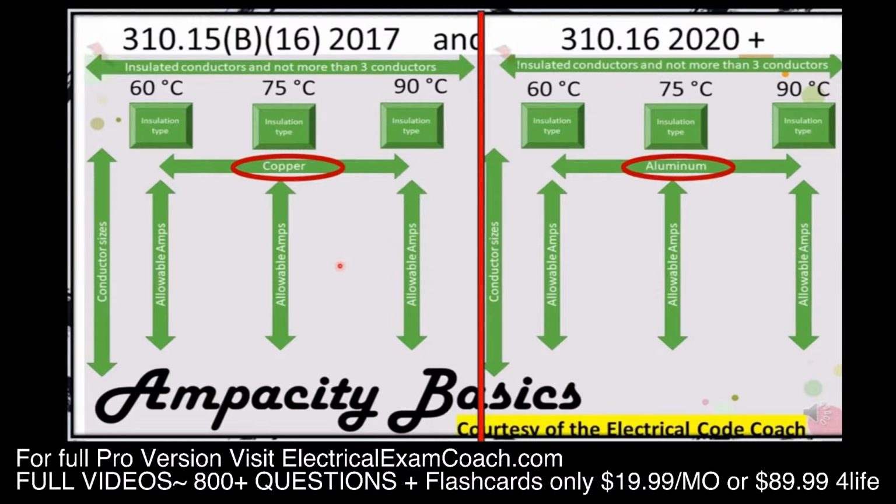So starting at the top, it gives us the scope of the table. We're not going to get into that right now. It comes later in the series. Then you'll notice there's a 60, 75, and 90-degree C columns. Below that are going to be the insulation types like THHN, THWN. On the left-hand side, you're going to have the conductor sizes, which is easy. And then in the middle, you'll find the allowable ampacity for each respective column. Now let's take these piece by piece and explain exactly how to use them.